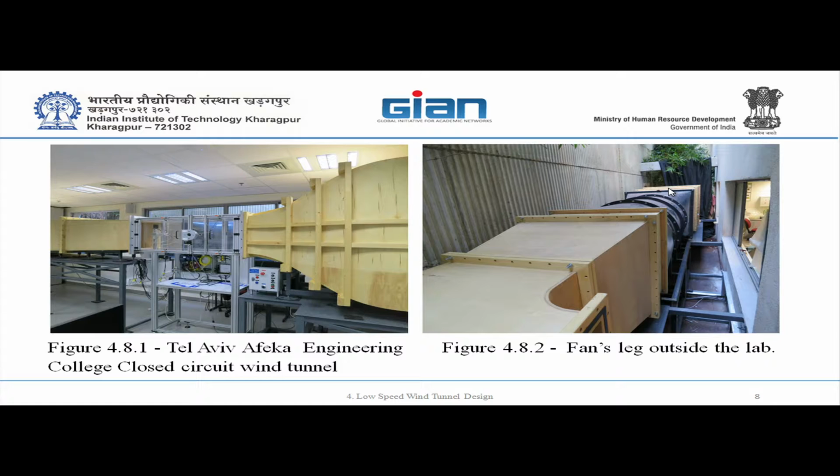There is an option for wide angle. I put here an optional wide angle diffuser, which I don't recommend having anywhere. If it's far away from the test section or settling chamber, not so bad, but I think in our case you can find a wide angle diffuser only ahead of the fan, where anyway everything is going to be garbled and mixed there. So I'm not so worried about it.